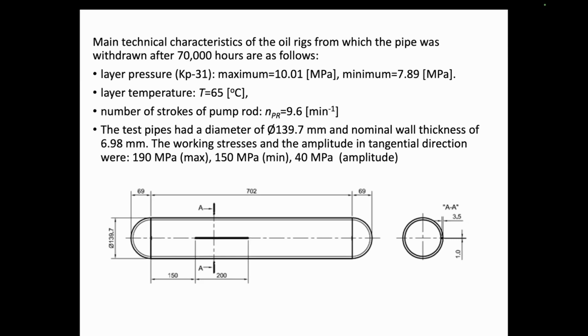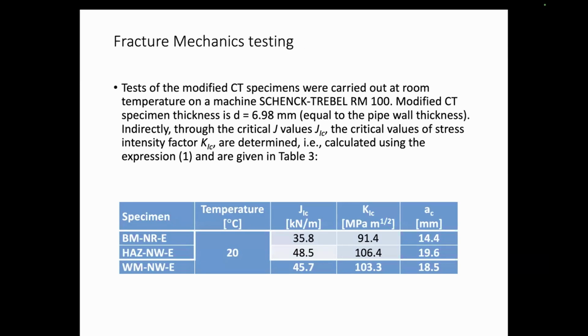So we even could do some strain. We could do fracture mechanics testing to get precise values for fracture toughness in the base metal, heat affected zone, and weld metal.